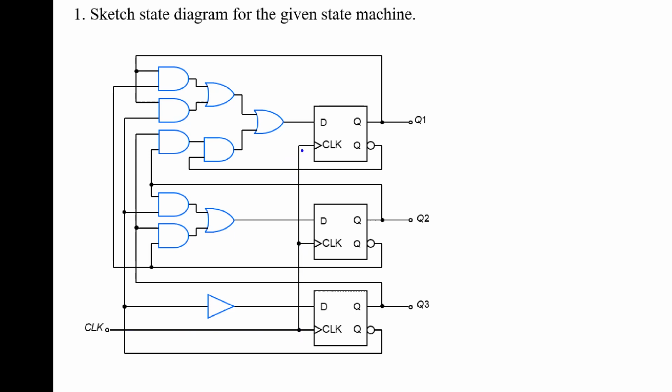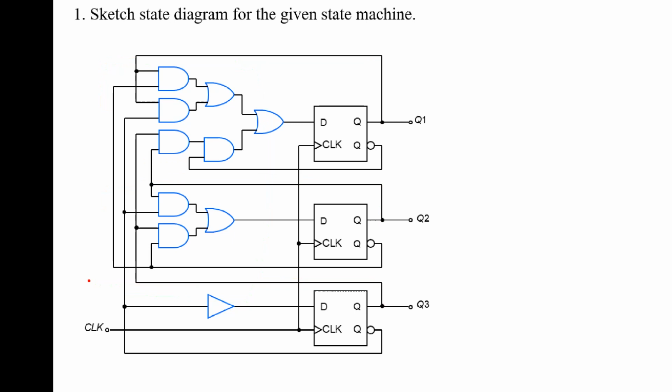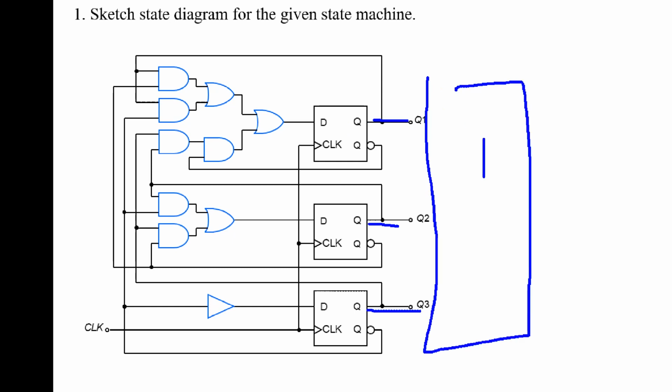The circuit F is the next state logic. The input of circuit F is coming from the flip-flops or state variables. And the output of this circuit connects directly to the output of the flip-flops, namely for circuit G. The output and the state are the same signal or same value.